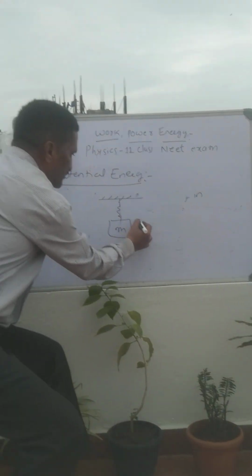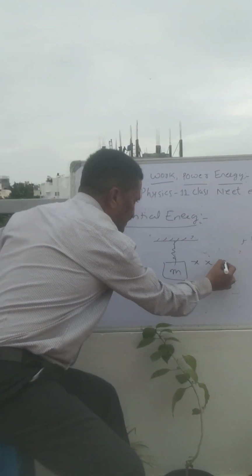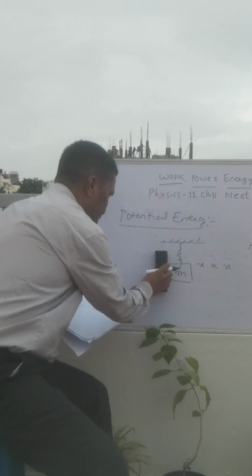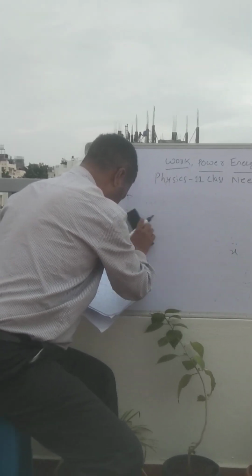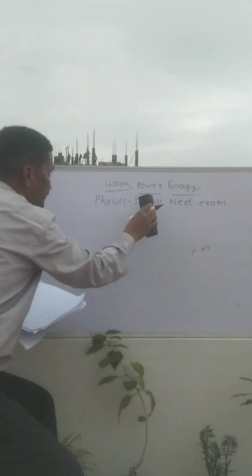And kinetic energy also. Potential energy is stored in the spring. When the mass displaces down, with displacement x, x dot is velocity and x double dot is acceleration, right? When it is coming down, some amount of energy will be stored in the spring. That is called potential energy. You can calculate such a system in the vibrational system, both the potential energy as well as the kinetic energy of the system. So these are the examples I have given for kinetic and potential energy.